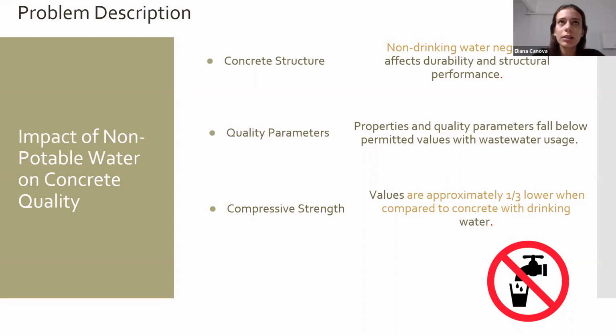In fact, it has been studied that water has a significant impact on the compressive strength of concrete, an impact that is perceived at 7, 14 and 28 days, and the values obtained are around 1 part in 3 lower than the values obtained for concrete made with drinking water.